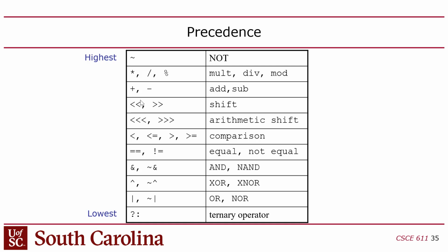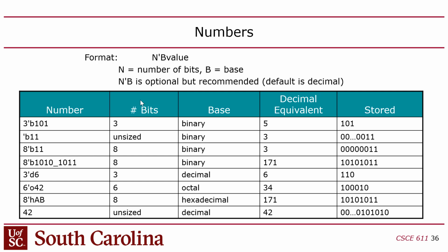Okay. I'll talk more about that when I get to test benches. And then I mentioned that whenever you have a number in Verilog, you should specify the bit width, followed by an apostrophe, the base, and the number. Now you're going to notice that even the textbook doesn't follow this rule all the time. I don't know why. And if you look at the code that we give you as part of the lab skeleton, there are even cases in there where we don't follow this. But it's good practice to specify bit widths. You guys with me? So I'll point out whenever that comes up.